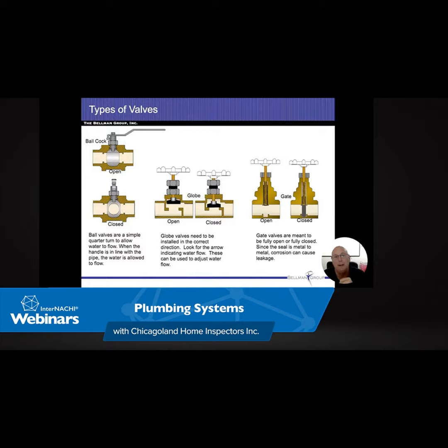When you start getting buildings like the Sears Tower, or the Willis Tower, or the John Hancock building, the taller buildings, they're actually going to have to have reservoirs in areas where they catch the water and then they pump it up the next 20 stories or 50 stories, whatever it is. You can't have a pump that's going to lift it all the way up that high and still maintain a good flow and a good steady amount of pressure. So they actually have holding areas and they fill them up.